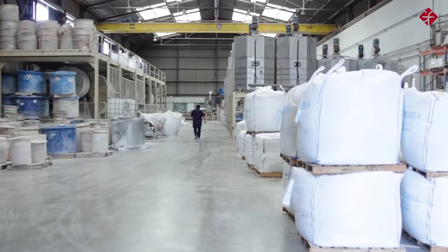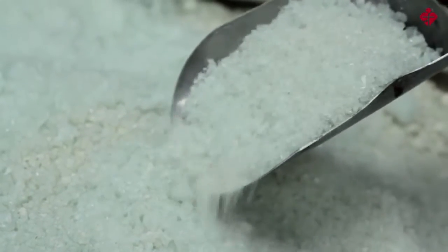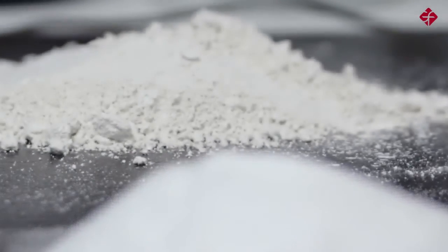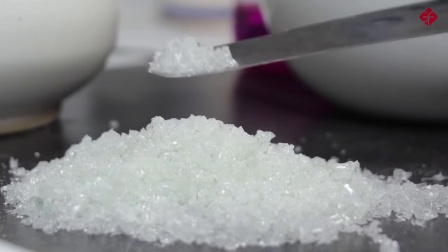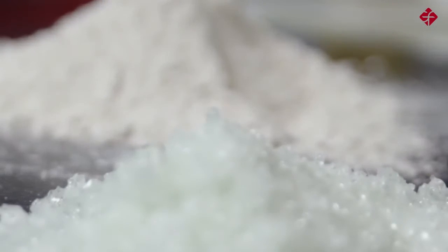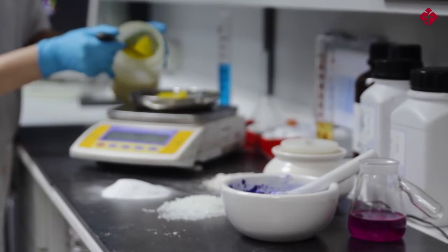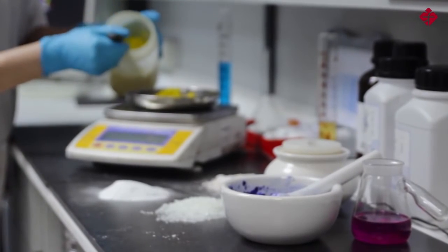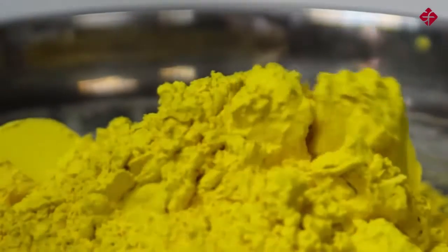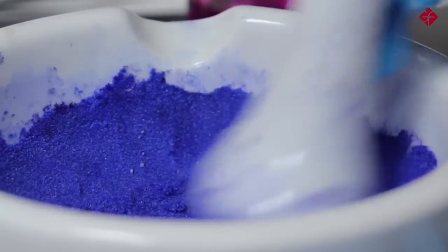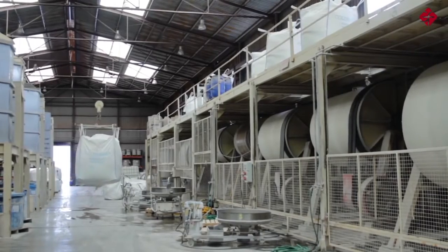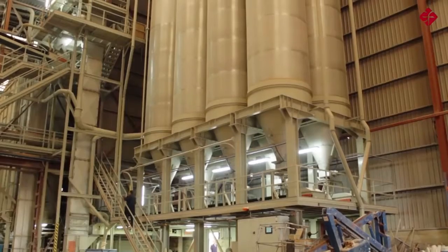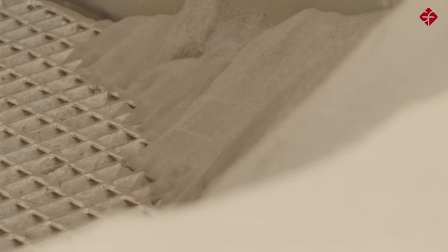The ceramic process begins with selecting the raw materials that we mix to create the tile, basically clay, feldspar, sand, carbonate and kaolin. As the raw materials are used just as they are extracted from the mines and the quarries, the first and most important thing we do is check the uniformity to ensure their properties remain consistent. To do this, the materials undergo a mechanical milling process that disperses the particles and reduces their size. Gaia Forés has its own glazing warehouse, silos and an unloading bay for the treated clay.